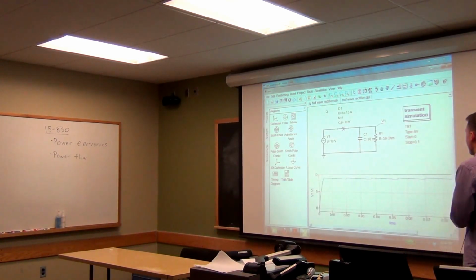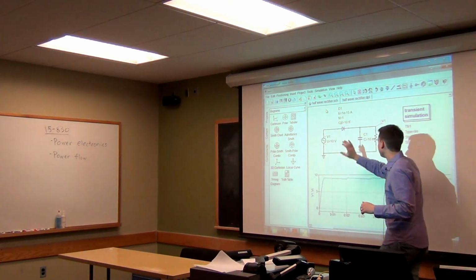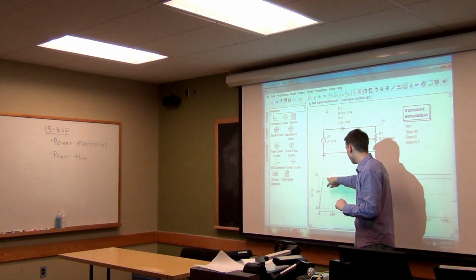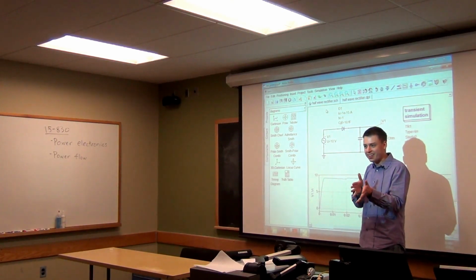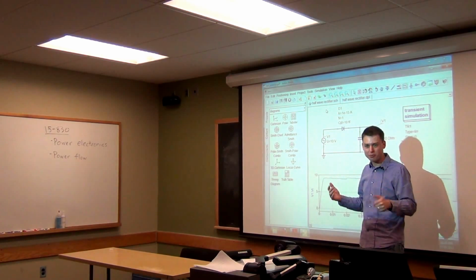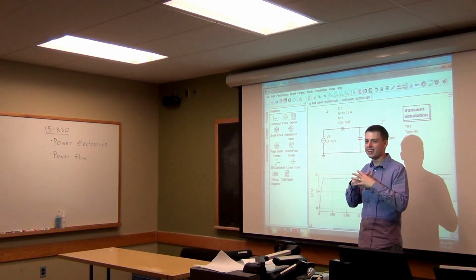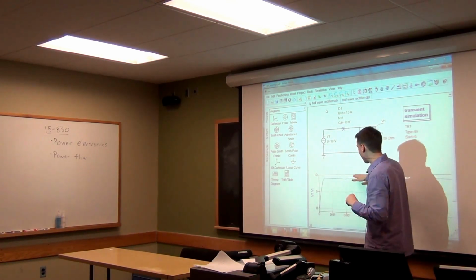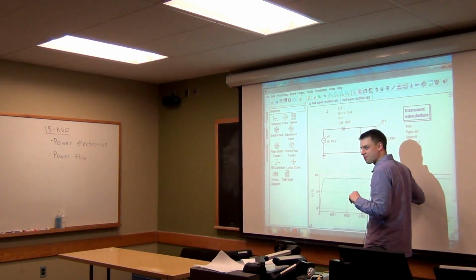Yeah. So approximately. There's always going to be a little bit of ripple here, because you can never quite completely flatten out a signal. But with a big enough capacitor, you can do pretty well. You can store enough charge that it's going to see approximately the same amount this whole time.